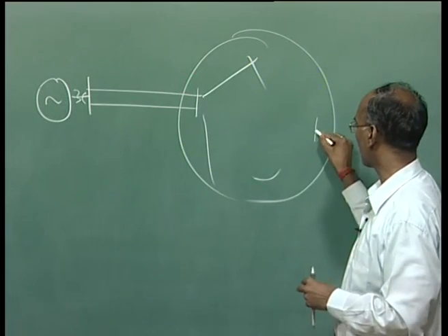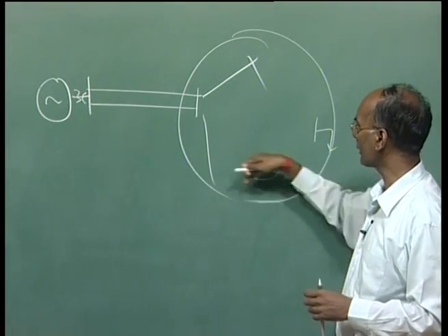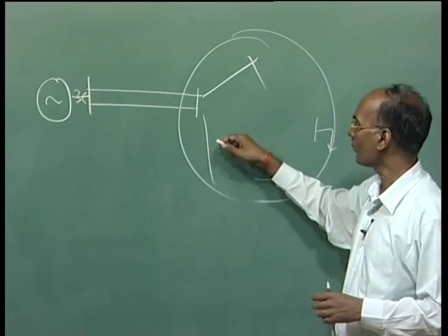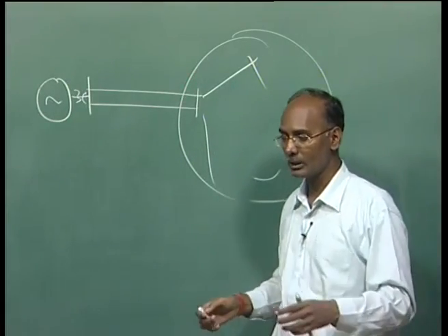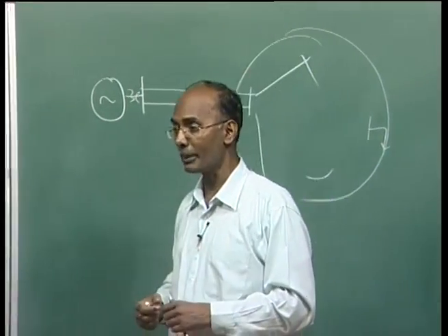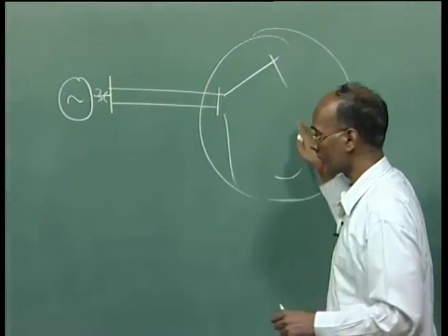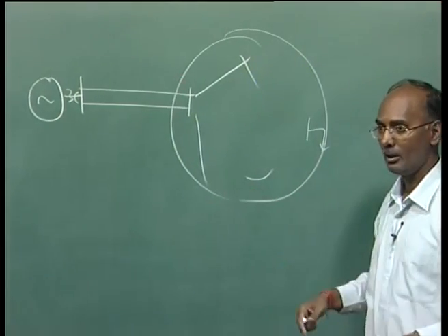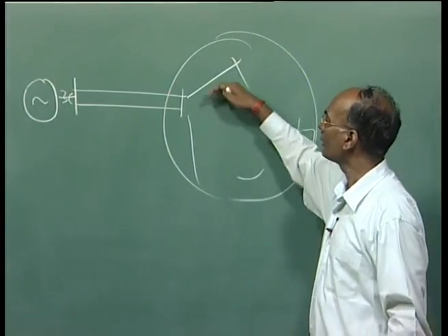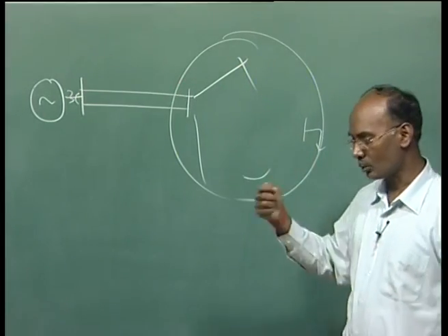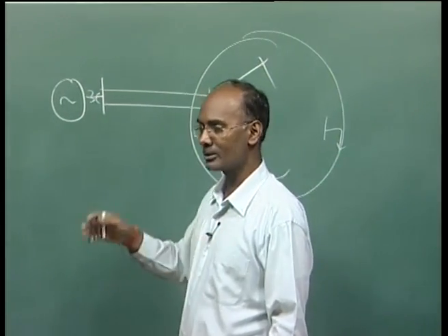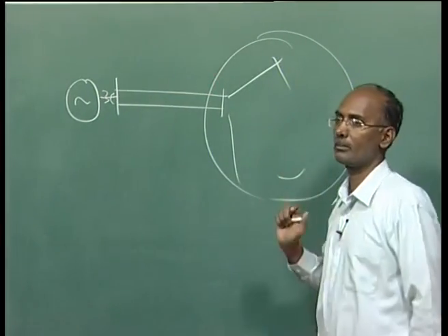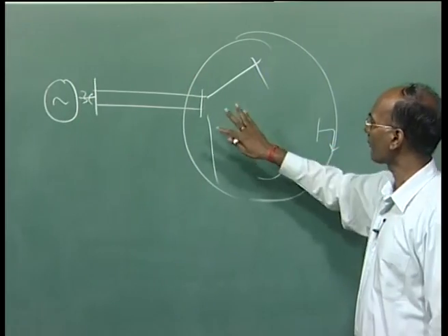Once you require the power here, now the question is how the redistribution of the power is going to take place, and what will be the effect, because earlier it was also loaded. Now some of the lines will be overloaded, and maybe some voltages may go below the lower limit or above the upper limit, depending upon the system criteria. So, we require certain new additions of the lines. We can go to various compensating devices like reactors, capacitors, etc., and then we have to go for these planning studies. Then you require the load flows.